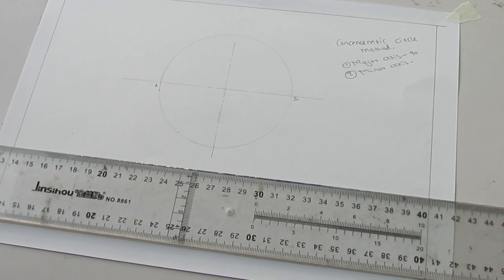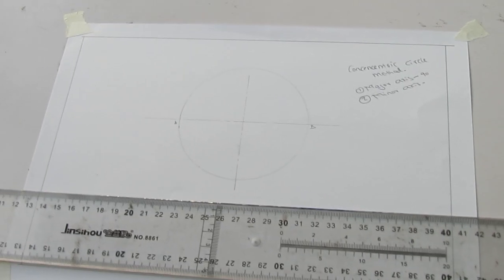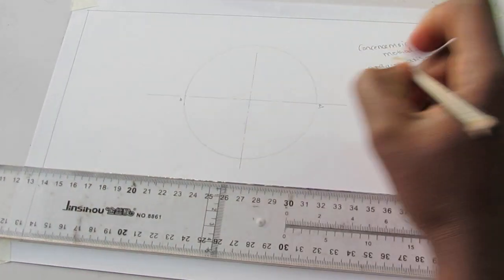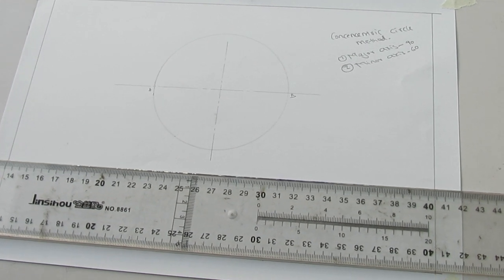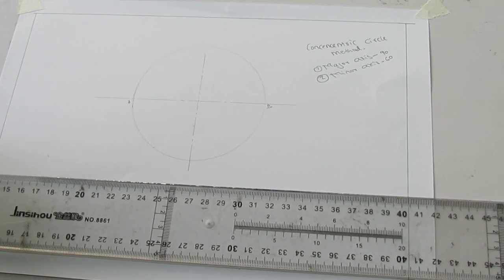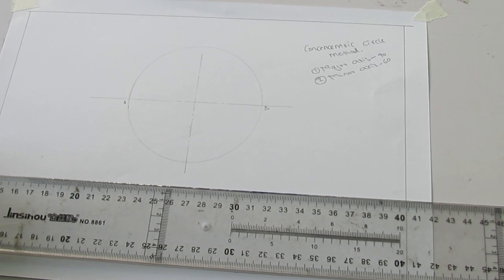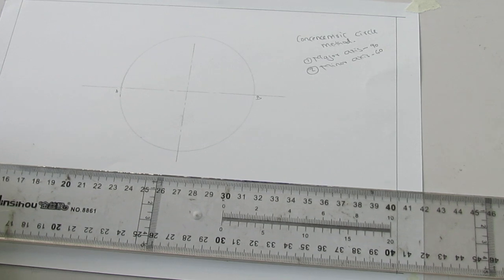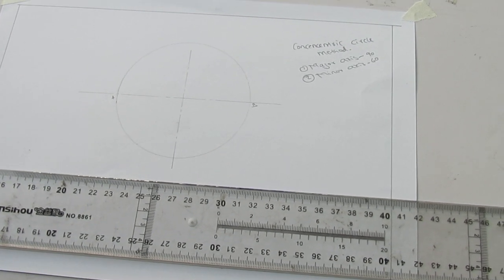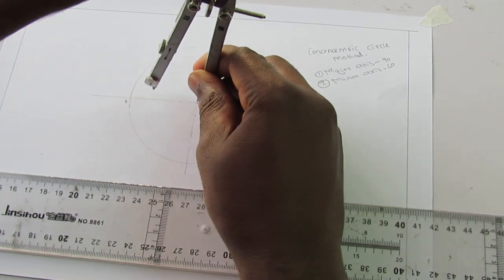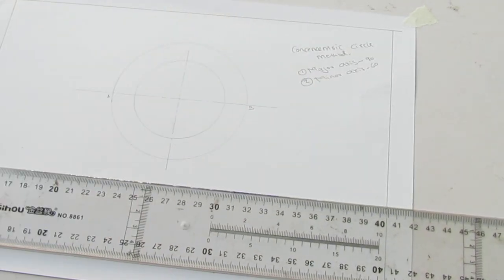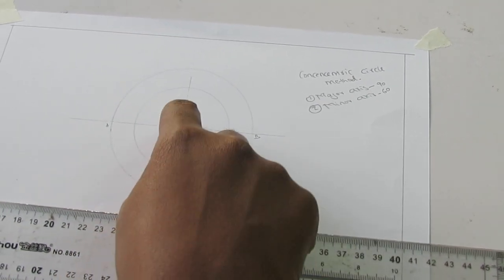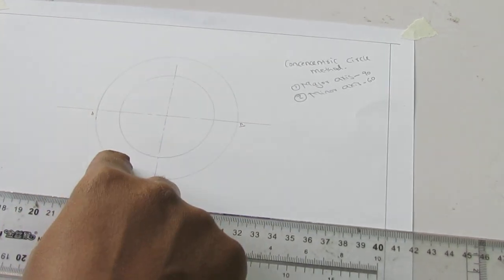Then we have got the minor axis. Let us do a minor axis of 30. So we want to use, no, that is too small. That is a radius. Let us use a minor axis of 60. So the radius is 30. So the next thing that you do is to draw a circle of radius 30. So this is my 30. Remember, all dimensions that I'm stating here are in millimeters. So with that 30, you draw a circle. So these circles are concentric. Why? I stood at the same center when drawing circle 1 and drawing circle 2.